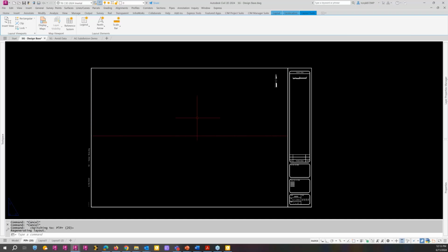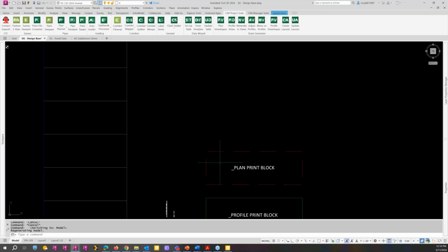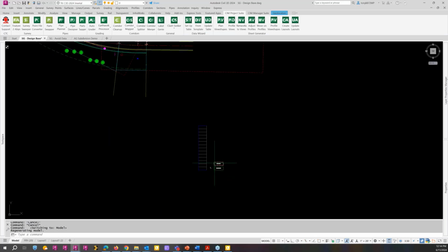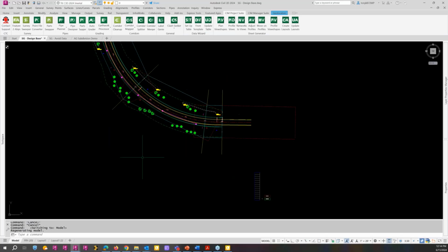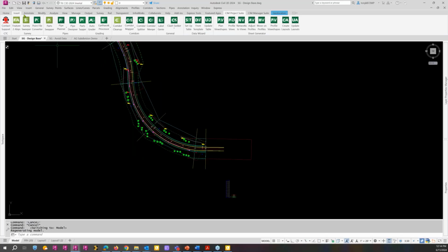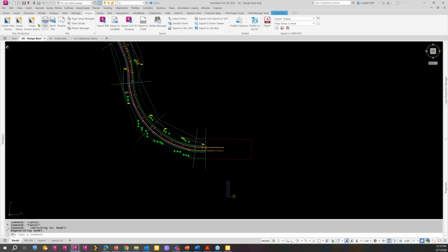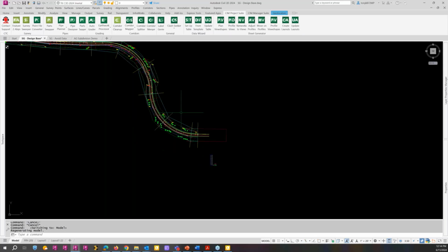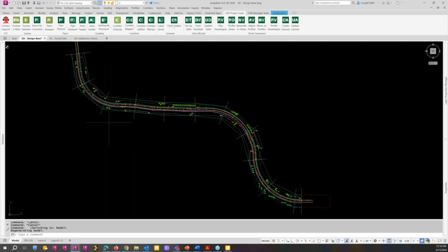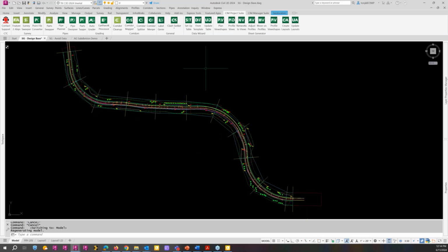So 20 scale, you'll know your lengths, you'll draw your block as such in here to help lay out your plan view shapes. It works a lot like the native output create view frames, but it's more versatile in that we can quickly, easily change things and then rerun it to get our view shapes and everything set before we actually create layouts. And I'm just going to go over today the layout portion of it, which is what we see right here in this example.